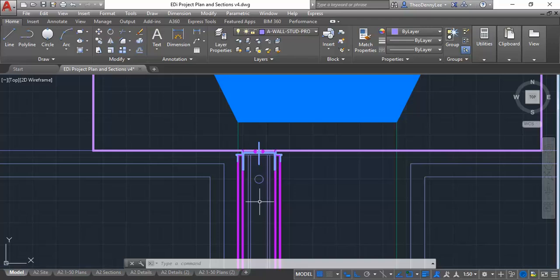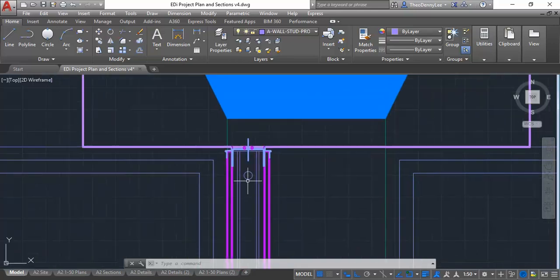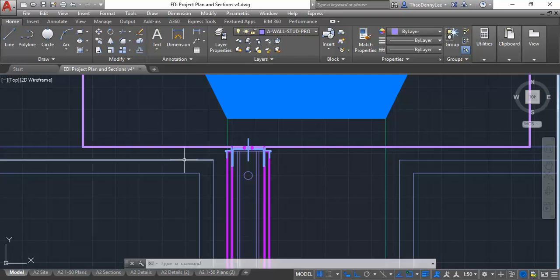The scale will work either way, but it really just comes down to practicalities. In the model tab, you can easily copy things from one detail to another, and work on a series of things without switching between views, so that can make it easier. But when you're working on the sheet, you've got a better idea how the text is going to fit in with that particular view in relation to other things on the sheet. So there are reasons for doing it both ways. In reality, working on a big project, you probably have some text in the model space and other text on the sheet. And it doesn't make a difference where you do it, because it comes up the same way no matter how you've made it. It comes up on the sheet.